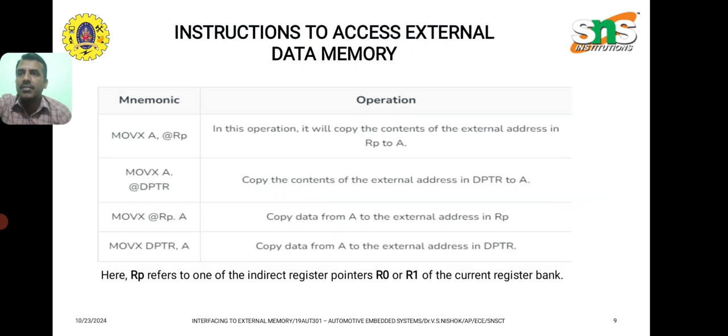And similarly for data memory. So instructions to access external data memory. For example, MOVX A, @Rp. In this operation, it will copy the contents of the external address in Rp to the accumulator. Similarly, MOVX A, @DPTR and further examples.